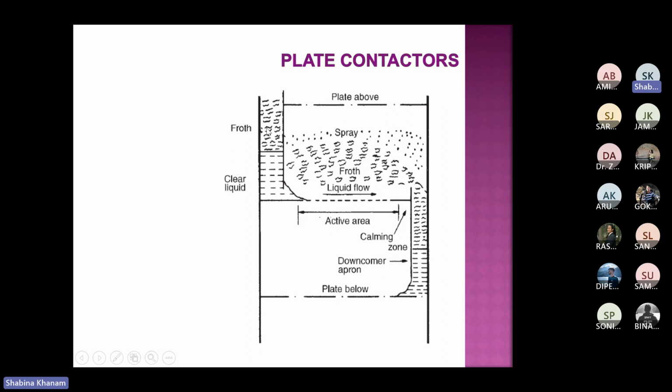Now, when the liquid is coming from the above plate, here we consider that no holes should be available, because liquid should stay over here and then move towards this. If we prepare holes here, liquid will start dripping from here, coming down from here, which we do not want.